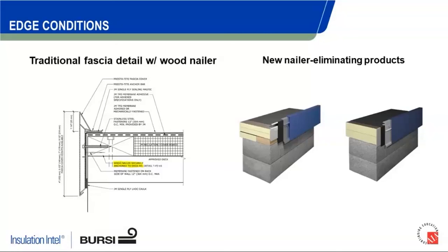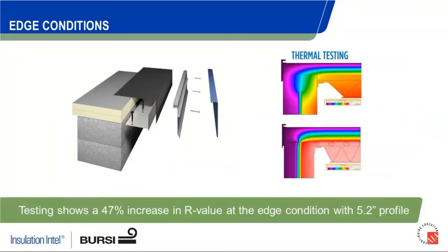Another view of that, you can see how those cleats are mechanically fastened down to the wall itself, and then the insulation can come all the way to the end, getting rid of that thermal issue around the perimeter of the building, which can be quite substantial and definitely worth paying attention to.